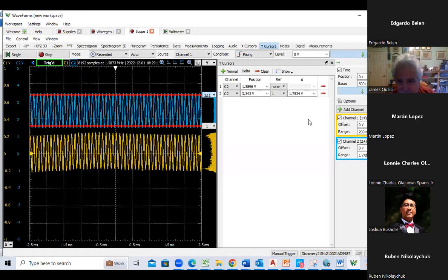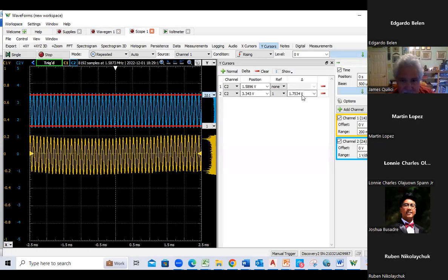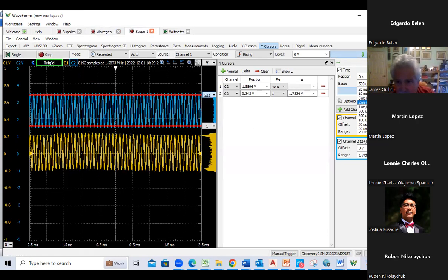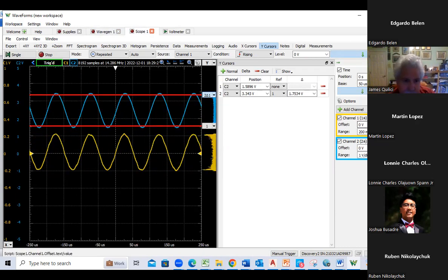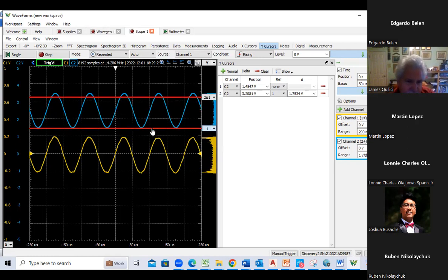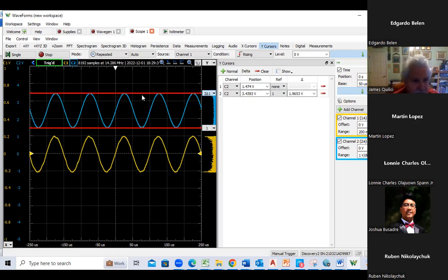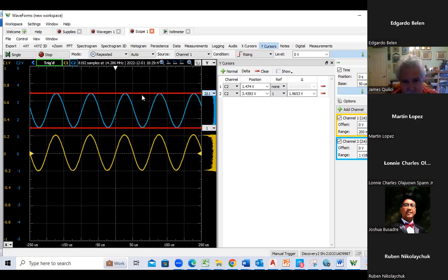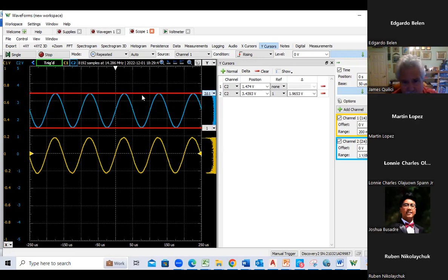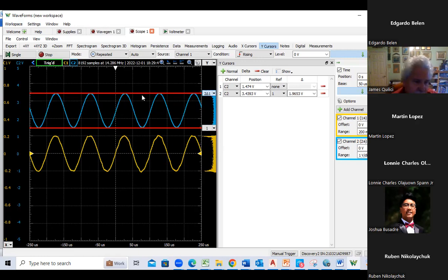So I got a little bit more gain out of that. It looks like here. Let me change the time base. Yeah, so actually there's a little more gain. We may not have fully been in the passband, but if you're using 10 kilohertz and capacitors above 1 microfarad, you'll most likely be in the passband. Okay, so that's still a gain of about 10, which is within spec. And I'm also in there. Yeah, that's all okay.